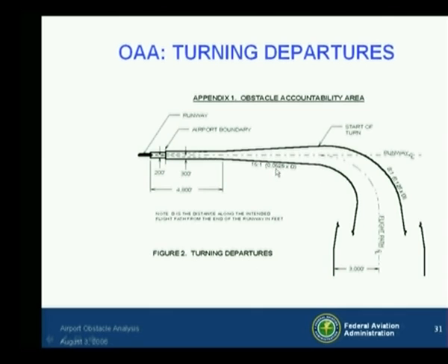Now remember this 0.0625D, which prescribed the 16-to-1 clearance splay for the straight-out departure. You need more room for maneuvering and winds and so forth. So in this case, the clearance plane is doubled to an 8-to-1 ratio, and it's actually got this number involved in it, which is 0.25 times D. And I'm not sure, but I think that's twice this. But at any rate, in the turn,